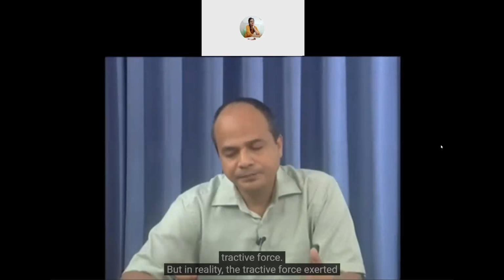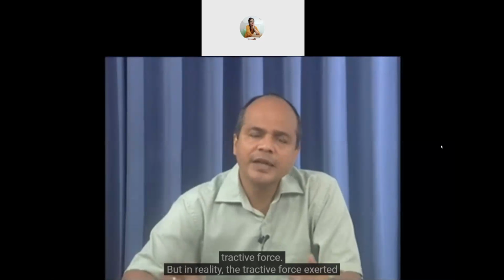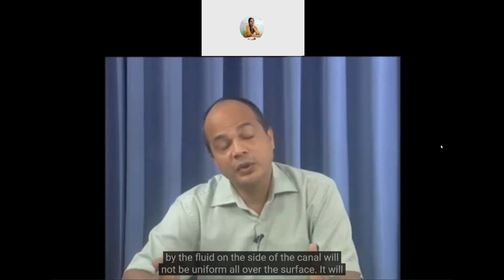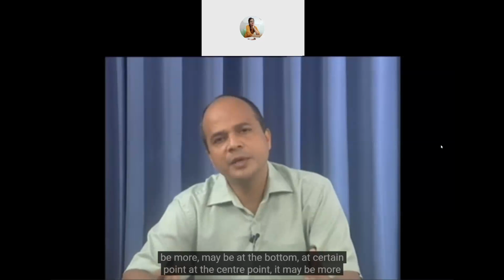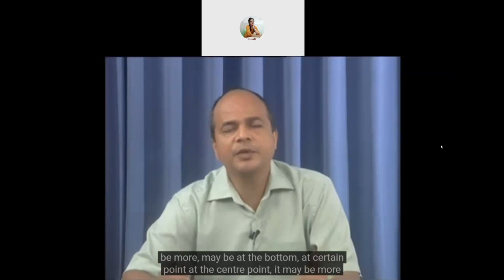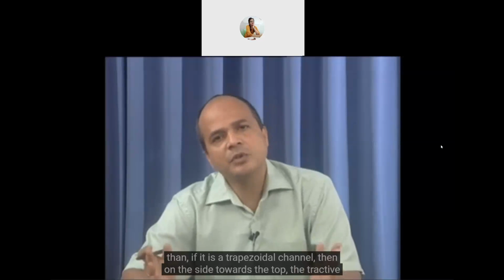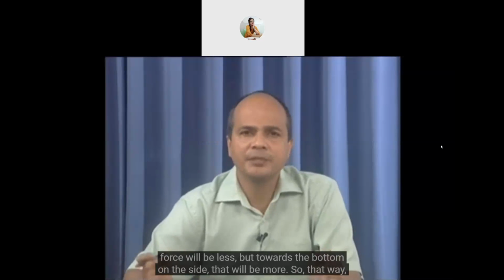But in reality, the tractive force exerted by the fluid on the sides of the canal will not be uniform all over the surface. It may be more at the bottom, at the center point. If it is a trapezoidal channel, then on the side towards the top the tractive force will be less, but towards the bottom of the side it will be more.